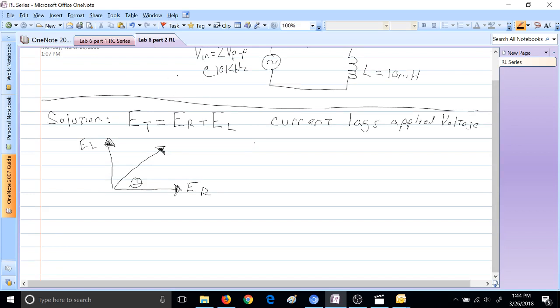Okay, continuing with our solution. Using Ohm's law, the voltage potential is equal to I times the circuit impedance. I couldn't put circuit here, but I think that's the way your lab writes it out. And we also have the individual components, the impedance across the entire circuit being the resistance plus the imaginary capacitive reactance.